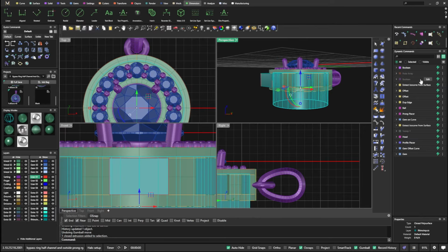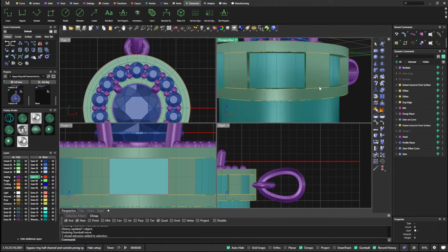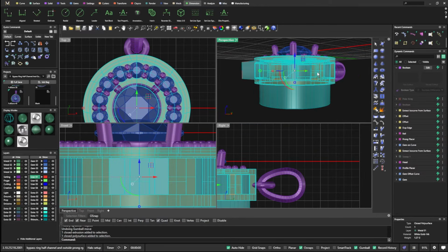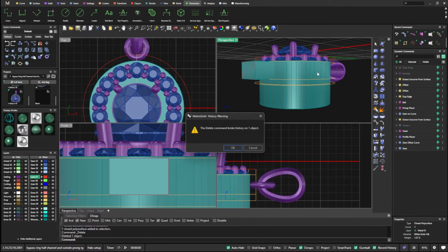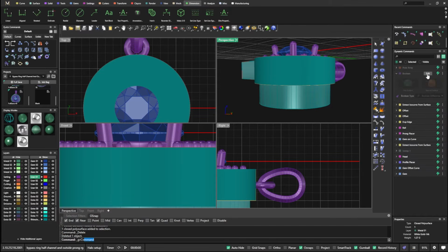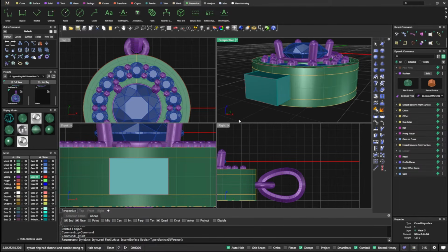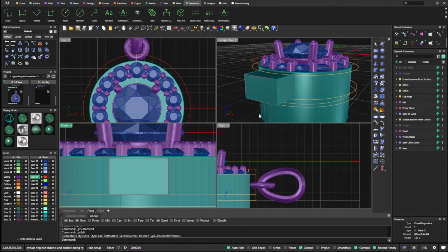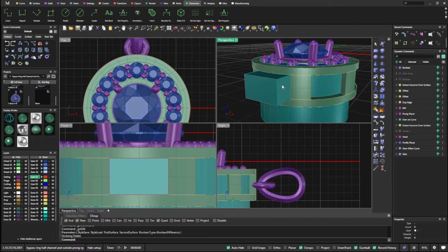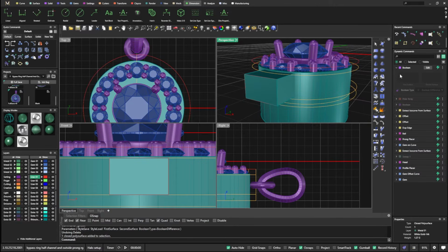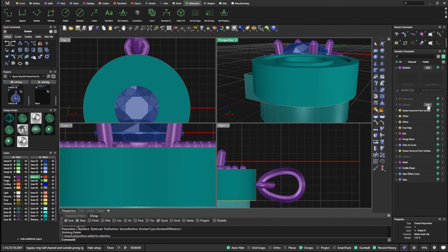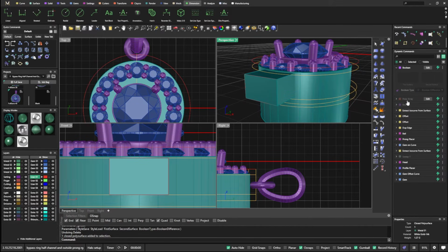Oh, okay. Our original surface, right? We need our original surface. So what we can do is go back and delete this one if we don't like it. Don't have to. We can go to this one here and we can edit, right? So now we're back to our original. We go to this curve, this extract ISO curve here. Where's my surface? I think I did something wrong there. Okay, there's that. Let's hide this for a second, and let's bring back this one, which should be on that layer. Okay, so Boolean, let's go over here and hit show.